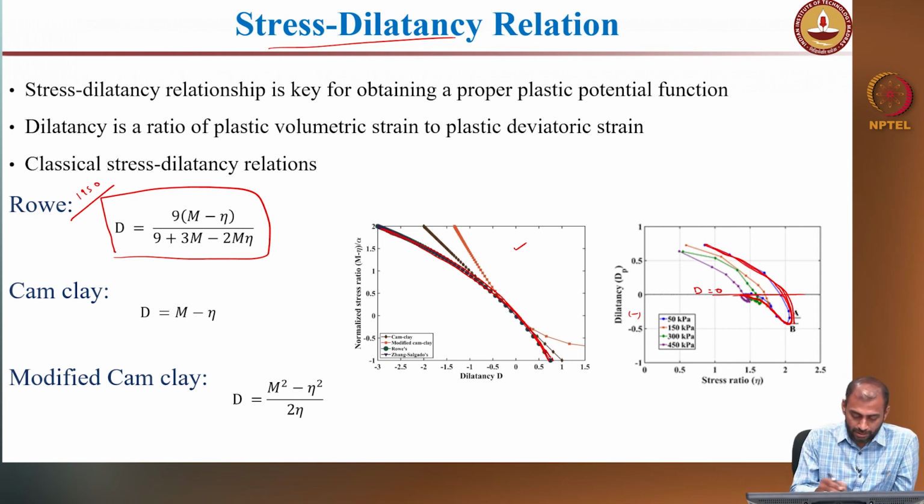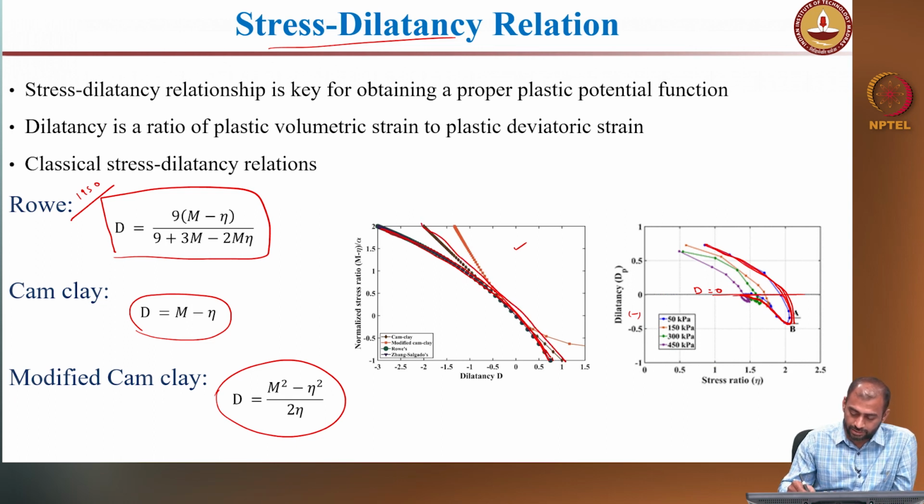We are also trying to compare it with the stress dilatancy relation given from Cam-Clay and the Modified Cam-Clay. You can see a linear relationship is obtained in the case of Cam-Clay, whereas a nonlinear curve is obtained when you use the stress dilatancy relation of Modified Cam-Clay, right.